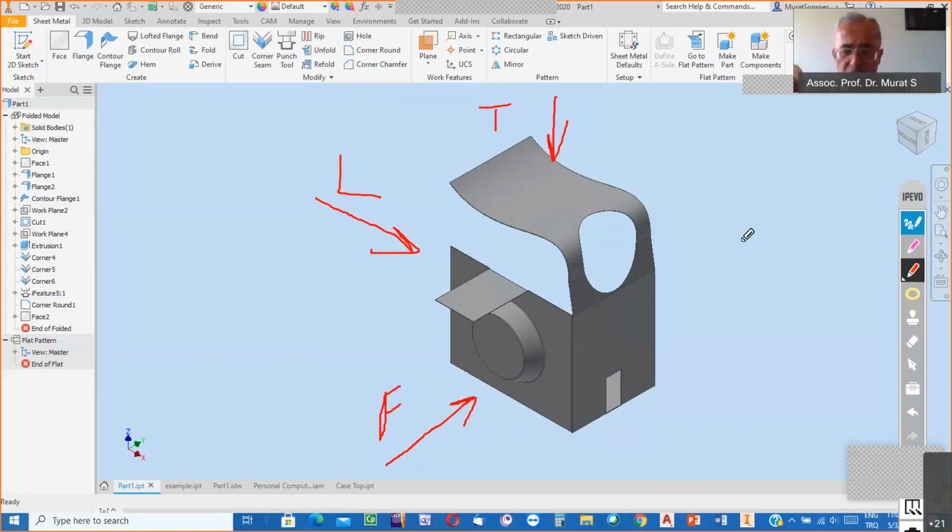It is the projection, okay? Well, it corresponds to the unfolded appearance of the sheet metal component. And that figure is to be spread over a prismatic, right prismatic sheet metal. And then along the boundaries of the development, the sheet metal can be cut and thereafter can be folded. Okay. Now, Inventor is quite capable, powerful in creating developments. For this sheet metal component, well, let us see how the development is created.